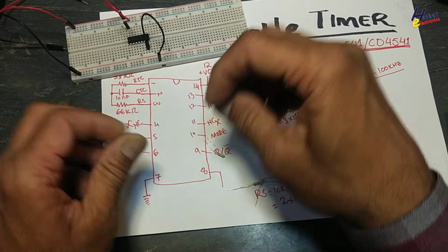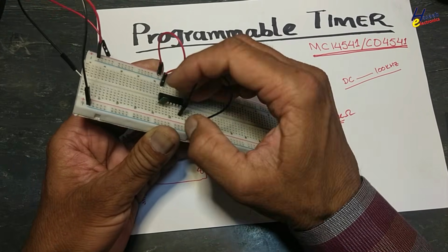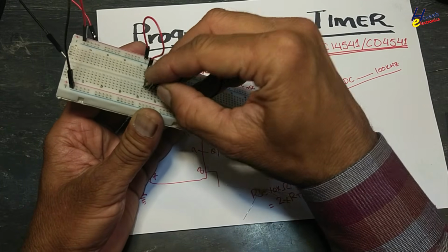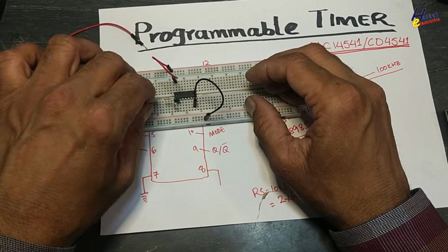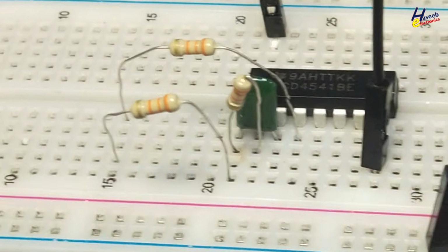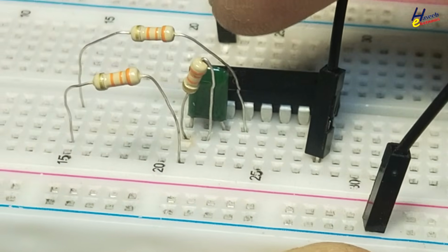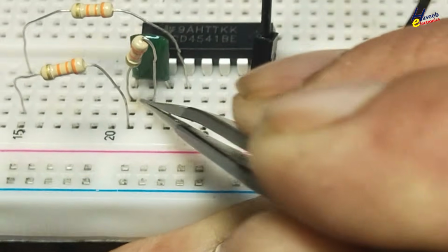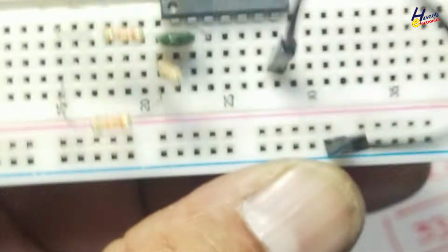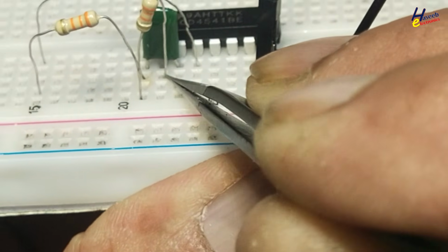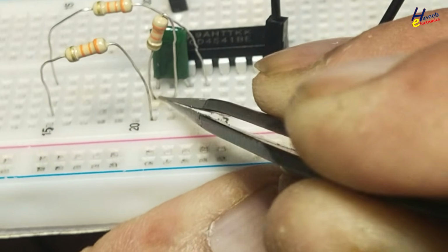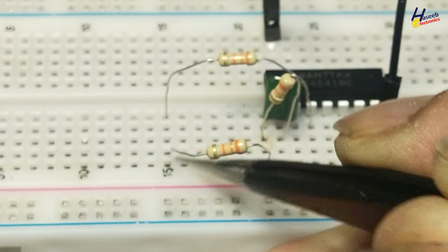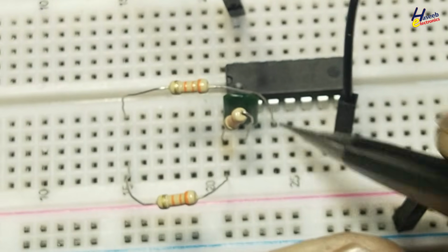Pin number 2, capacitor. Resistor at pin number 1. Capacitor at pin number 2. The second side of the capacitor is connected at an open point, that is not connected to the IC. And we connected a resistor at pin number 1, 33k. At the same point with the 33k, we connected another resistor, 33k plus 33k, to pin number 3.